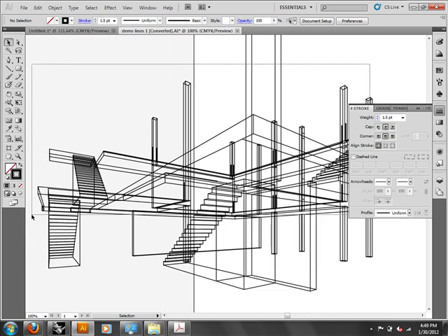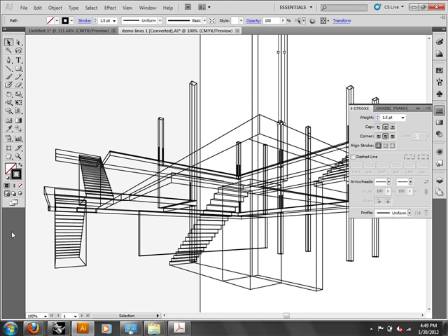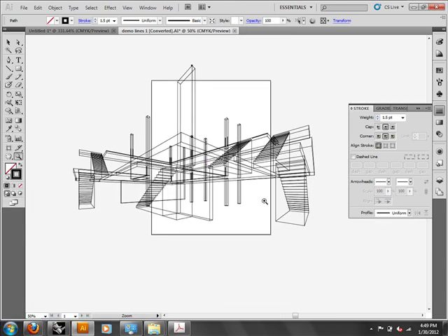So again, you can scale things explicitly by going into Object, Transform, and then Scale. So if you want a particular size, you do that. And with the orthographic diagrams and the axons, which are measurable, you might want to use the percentages. Or at least be consistent in how you do it. So every time you export one, you always bring it in, and it's always 50% of the size or something like that. That's one way to maintain consistency in your drawings.